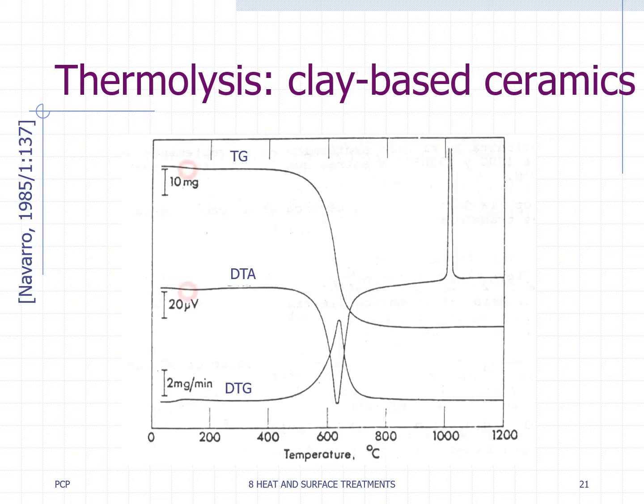In the case of clay-based ceramics, we notice the loss of water, both adsorbed and combined, at increasing temperatures, as well as the decomposition of kaolinite into metakaolin at temperatures before the sintering path is reached.